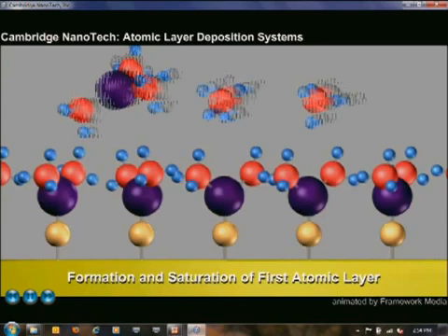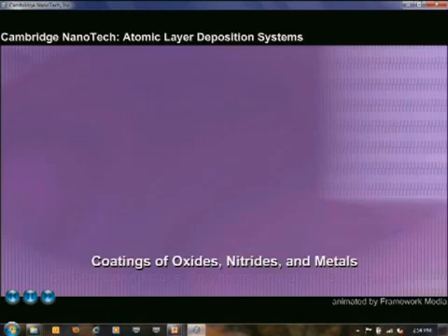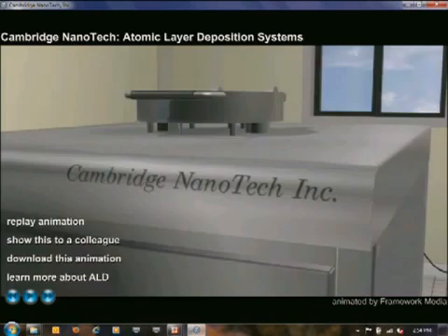It's a gas that gets into all these little crevices. So not only is it a great way to create dielectrics for MOS devices, but it's a great way to create very deep trench capacitors with very high capacitor densities. Okay, so a little animation of how that works. And let me go back to this module here. This is an actual SEM of a deep trench that has been coated with a very thin layer, 18 nanometers of alumina, using the exact process that you just saw.